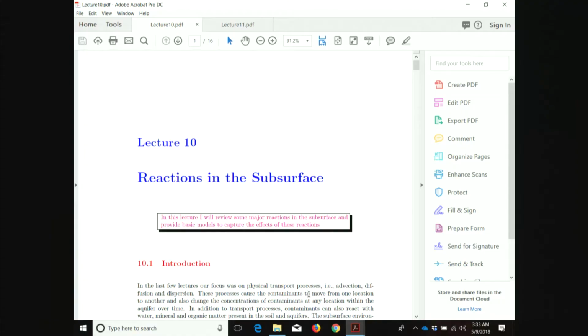One, it causes mixing in directions other than normal to the groundwater flow, and it also causes mixing in the direction of the groundwater flow. The mixing in the direction of the groundwater flow is obviously the most, and mixing in the transverse and vertical directions is less, usually about a tenth or a fifth of the mixing that takes place in the longitudinal axis. I also talked about how to get dispersivity data.